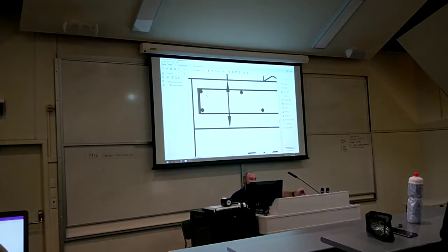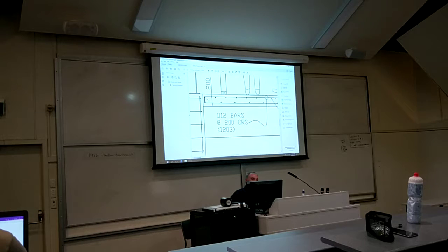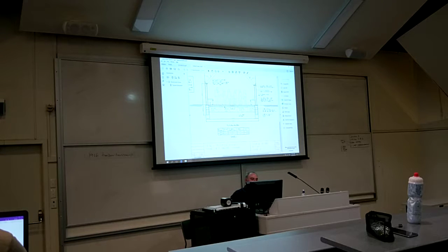As far to the edge as possible. So if I tell you the minimum concrete cover is 40, you push the bar right up against the 40 where possible. All right? Once again, I'll cover that in the lecture. But I just wanted to be sure that you knew that even you guys, with the modern age now, you all zoom in on your PDFs to sort of like 0.5 millimetre, and then you start picking me up on what's right and what's wrong.